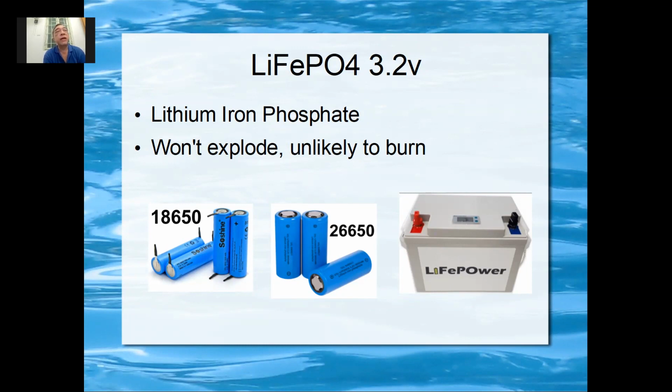If you want to connect them in series, you can connect them in series to use it, but you cannot connect them in series to charge. You will have a problem. So if you need 48 volt, you cannot connect 4 of these 12 volt lithium battery packs together in series and charge.